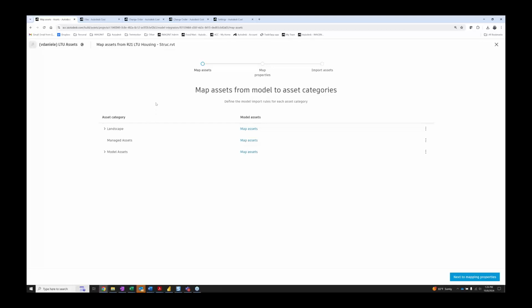In those 3D views within the ACC, I'll show the different status colors, but it will actually use a color scheme to apply those colors to the assets within that 3D environment. So you can start to view either construction project progress or potentially different statuses of maintenance. If the ticket's created and it's linked to the object and it requires maintenance, we can have those flag in a certain color.